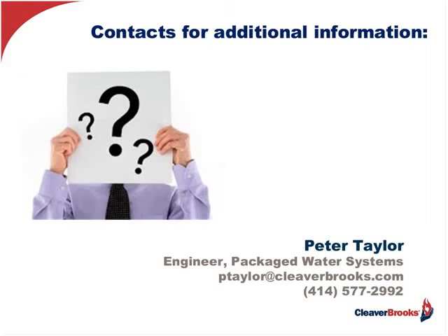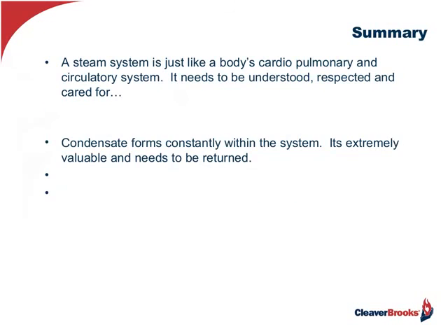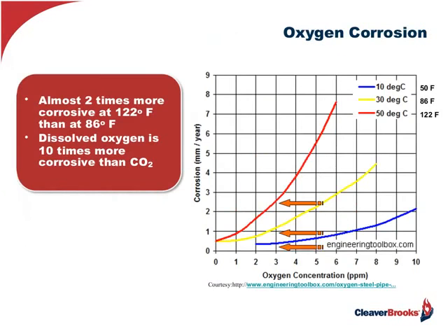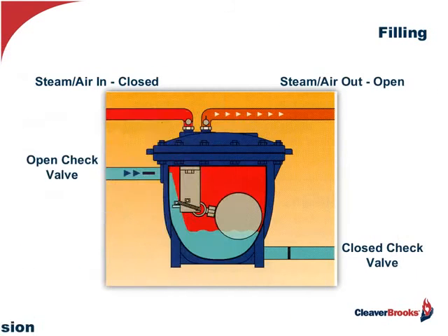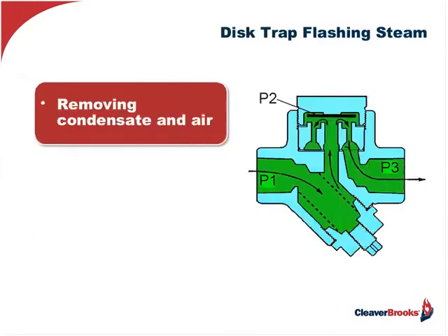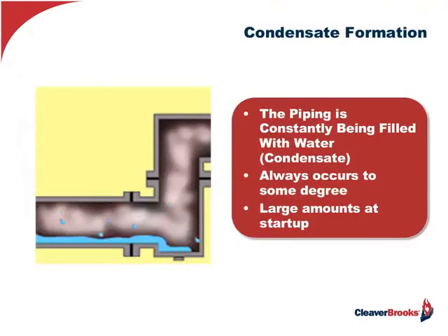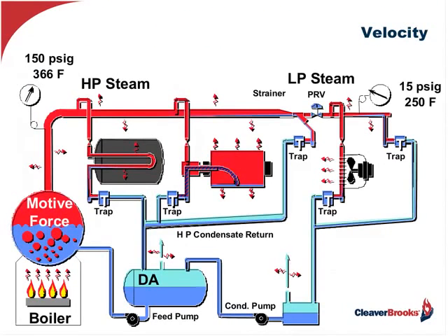Okay. And you showed a diagram previously, which has piping to and from a heat exchanger. This person has problems with waterlogging. Any suggestions? Let's see if we can get back to that. Yep, there we go. Right here, you can see this heat exchanger that's kind of filling up with water, with condensate, which means that my trap is backing up, okay? The back pressure is too great, and I'm starting to back up into my heat exchanger.